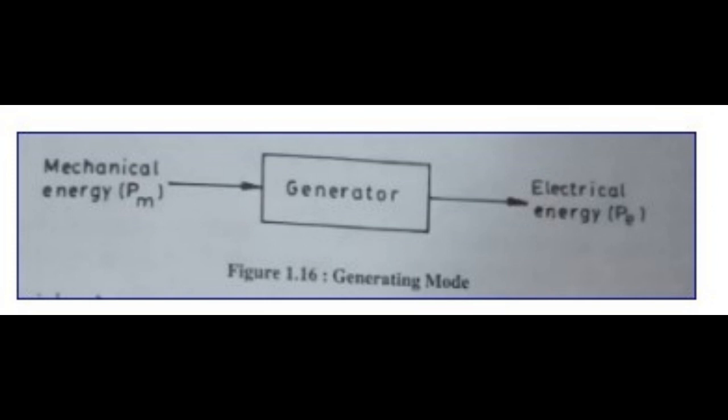1. Stator, 2. Rotor, and 3. Windings. 1. Stator. It acts as the outer cover of the whole machine to protect it from rain, dust, heat and bad climates. The main function of this part is to provide path for magnetic flux. It is the static part of the electric machine. 2. Rotor. It is the rotating part of the machine.